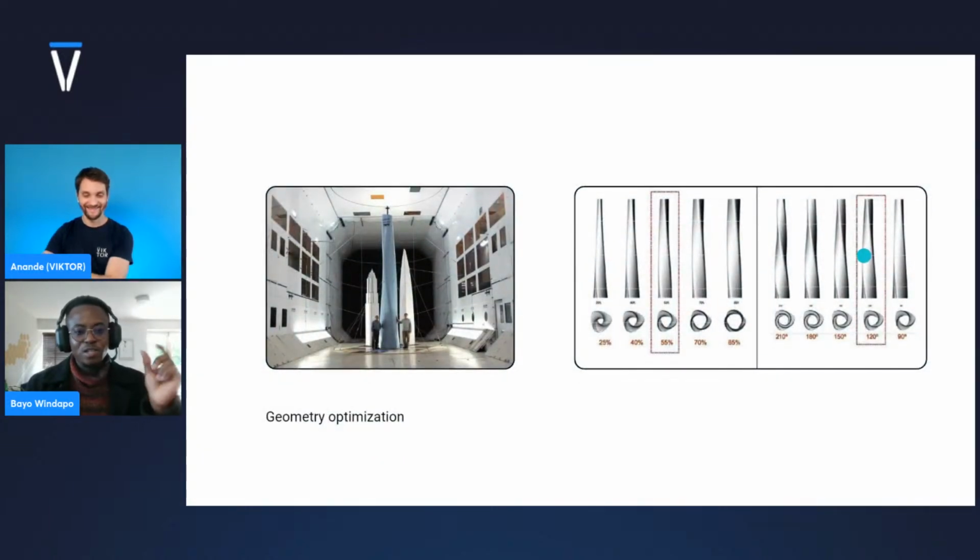If you saw the script I did previously, it was actually this building. I was trying to mimic what they were doing there. I find that to be quite a nice way of learning as well. I just copy what other architects have done, as a way of building up my own skills. What they came up with was that the one that twisted at 55% and 120%, when they did CFD analysis, that's computational fluid dynamics, was the one that withstood those wind pressures the most. And then they also confirmed it using a wind tunnel, with quite a large scale model. You can see how big that model is.